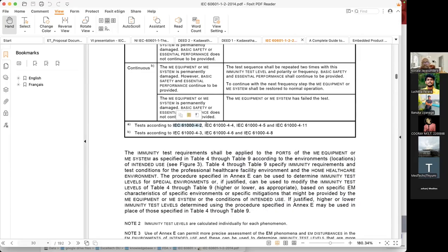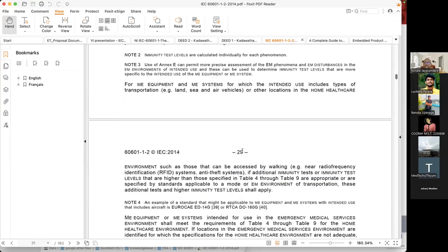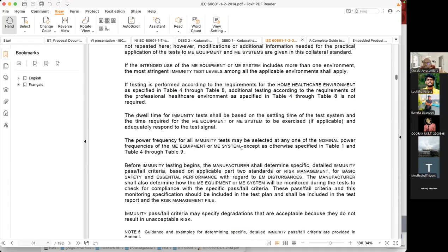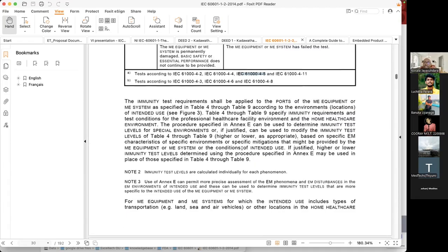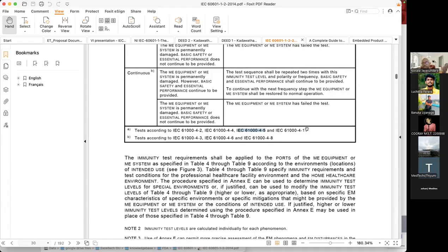Those tests are referring to other IEC standards that you have to adhere to. So you have to go to those documents and make sure that tests are done to those requirements. Normally, you don't have to build these test devices. There are third-party companies who are doing those tests for you. The only thing is, your circuit design should adhere to these tests. Otherwise, the third-party companies will say, "Look, your product failed." Then you have to go back to formula, redesign it, test it yourself, and then go to the standard bodies in another 1 year or so.